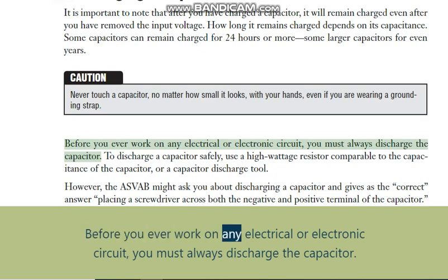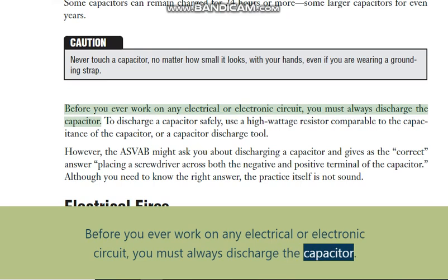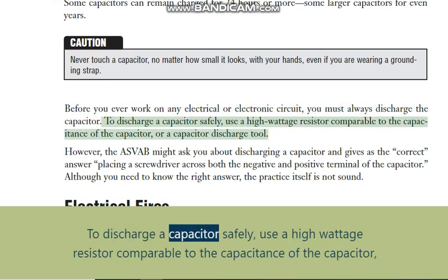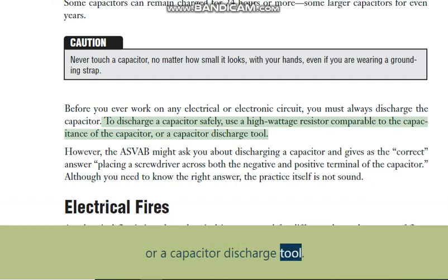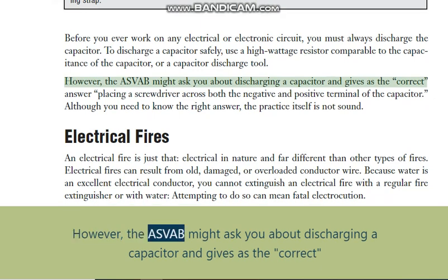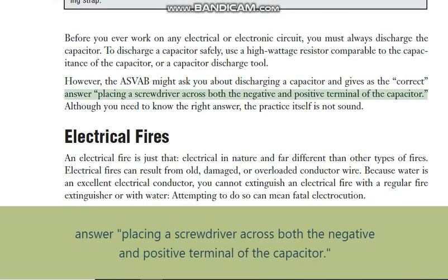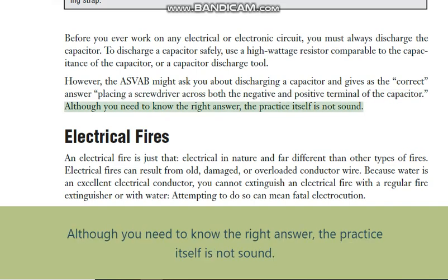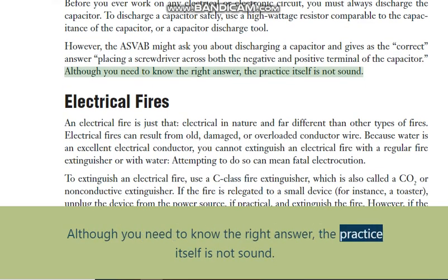Before you ever work on any electrical or electronic circuit, you must always discharge the capacitor. To discharge a capacitor safely, use a high wattage resistor comparable to the capacitance of the capacitor, or a capacitor discharge tool. However, the ASVAB might ask you about discharging a capacitor, and gives as the correct answer placing a screwdriver across both the negative and positive terminal of the capacitor. Although you need to know the right answer, the practice itself is not sound.